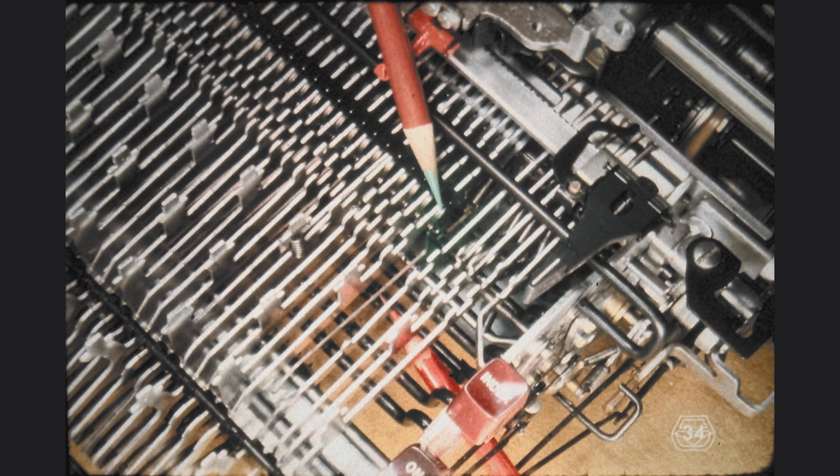Let us now do a bit of reviewing. It is up to the interposer, red pencil, to select or filter out latches, and thus determine which mechanism to use. Through the proper latch selection, the machine determines just how much tilt motion or rotate motion should be used to position the element so that it produces the character depressed by the operator.